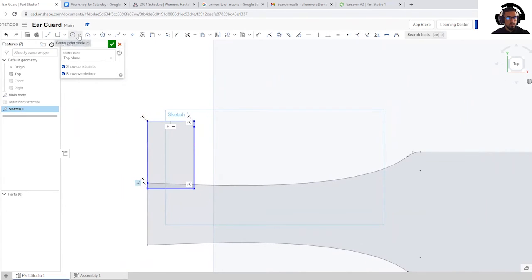And I want to click on the circle now because I want it to have that nice little curvature shape. First I will show you the three types of circles they allow you to do. They allow you to create an ellipse, which is not a perfect circle, but it allows you to elongate it and manipulate it however you please to get the desired shape that you like. You have a 3-point circle, and you also have a center point circle. For now, we will be using the center point circle.